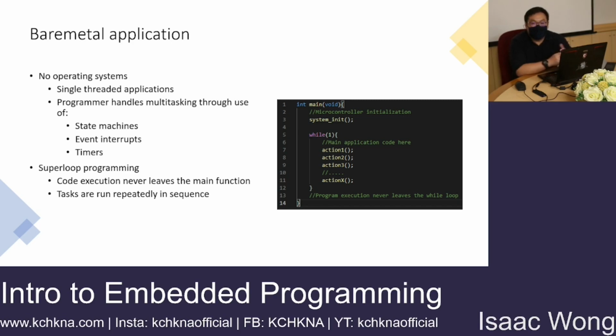Okay, so this usually requires you to configure the peripherals themselves. For example, I have a UART. A UART is a communication protocol that talks to other devices. Let's say I have another device that sends data to my microcontroller. My UART will trigger a receive interrupt. This interrupt will be handled by another separate block in the microcontroller, so it's not handled by the CPU. It's called an interrupt controller. Its full name is Nested Vector Interrupt Controller, NVIC for short. This interrupt controller will take over the execution temporarily, or rather, it tells the CPU to go to another part of the code. The CPU immediately moves to that part of the code, runs it, and when it finishes, it returns execution back to where it left off.